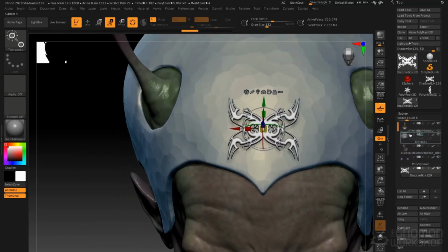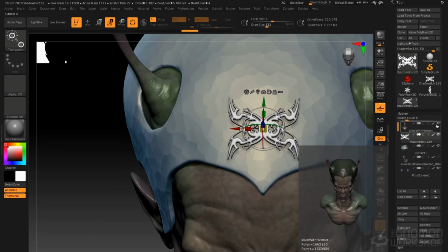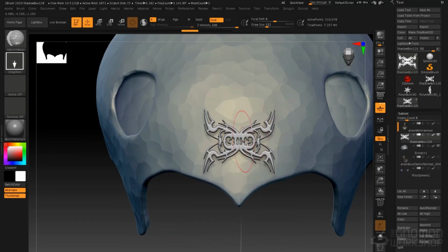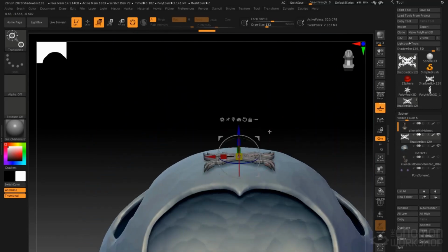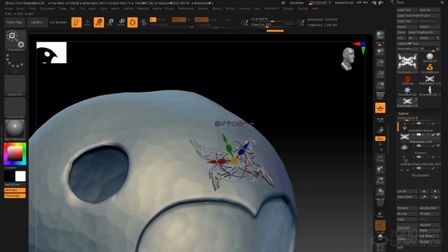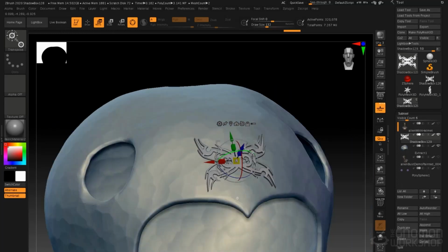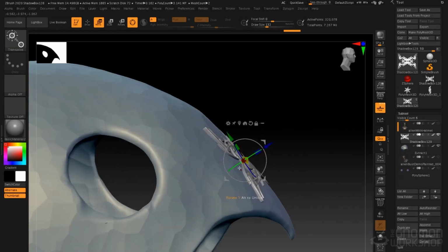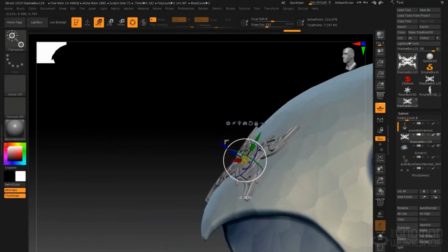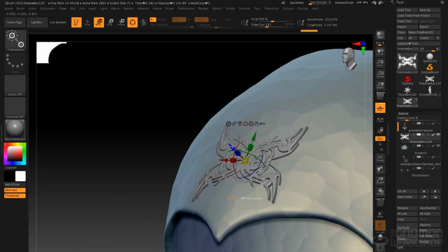Here you see we've got our insignia, and we've got our helmet right there. Just turn off visibility on all the other objects, so it's just these two items. Click on the insignia, drag, and let go off the model, and it's matching it to the surface underneath. So if I take transpose, I can countersink that, and it should line up right up with that surface, as you can see there. So it's perfect for taking insignia, tracery, all sorts of different decorative motifs, and conforming it to the shape beneath it.